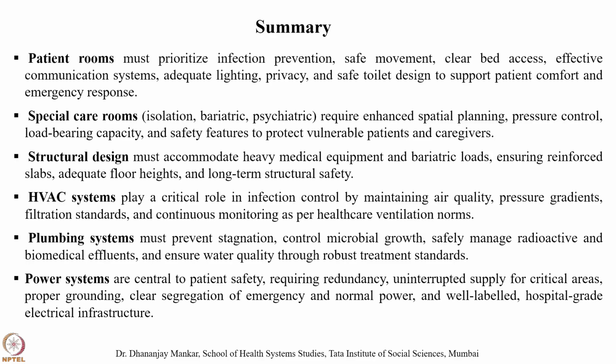The power system is very important and is to be identified as central to patient safety, requiring redundancy and uninterrupted flow for the critical areas, where you cannot afford a power stop. Proper grounding and clear segregation of emergency and normal power are very important, along with well labeled, hospital grade electrical infrastructure. So with this we come to an end to this